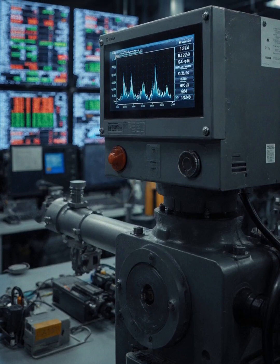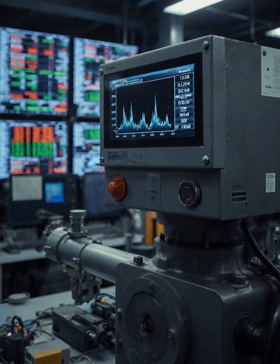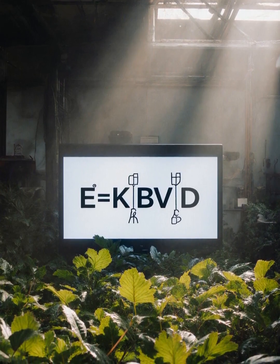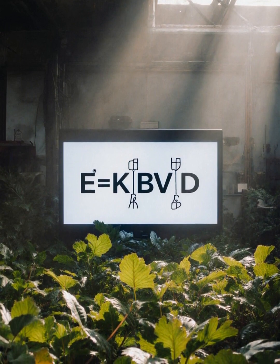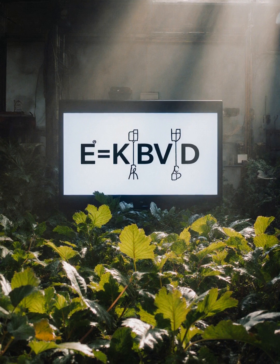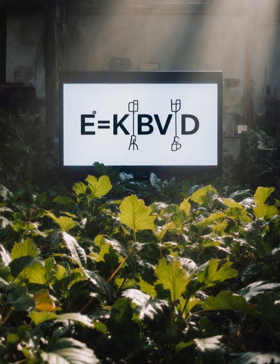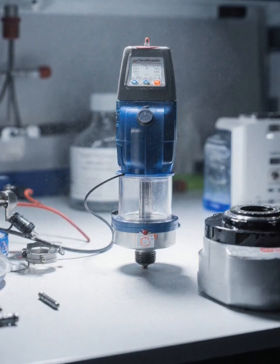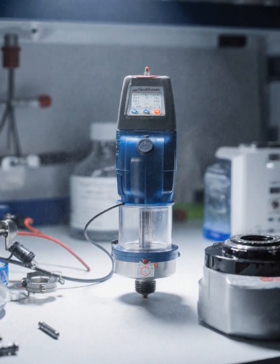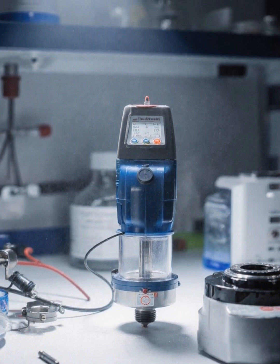The voltage sensed by the electrodes is further processed by the transmitter to give a standardized output signal or displayed in appropriate engineering units. Electromagnetic flow meters are based on Faraday's law of electromagnetic induction. Formula: E equals K times B times V times D, where E is induced voltage, K is flow tube constant, B is magnetic field strength, D is electrode spacing, and V is mean flow velocity.